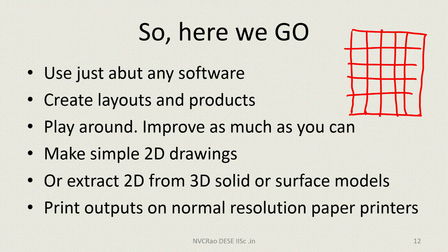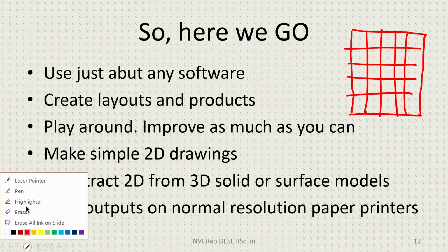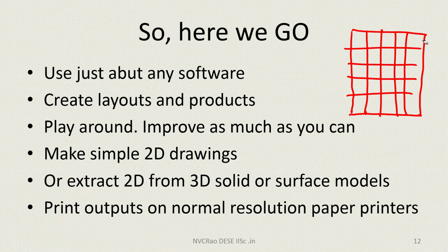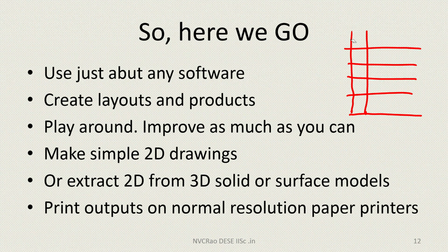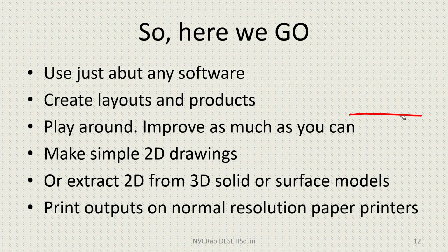Then in that case you can see, besides the total dimensions, is there any distortion in the middle also? Seen that, no? Besides the overall width of the dimensions, one of the important things is to calibrate your plotter, and the earlier you do, the better it is.